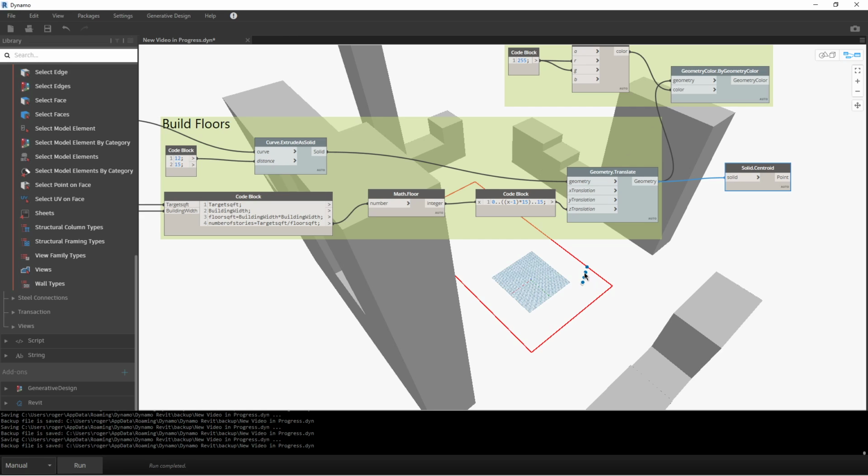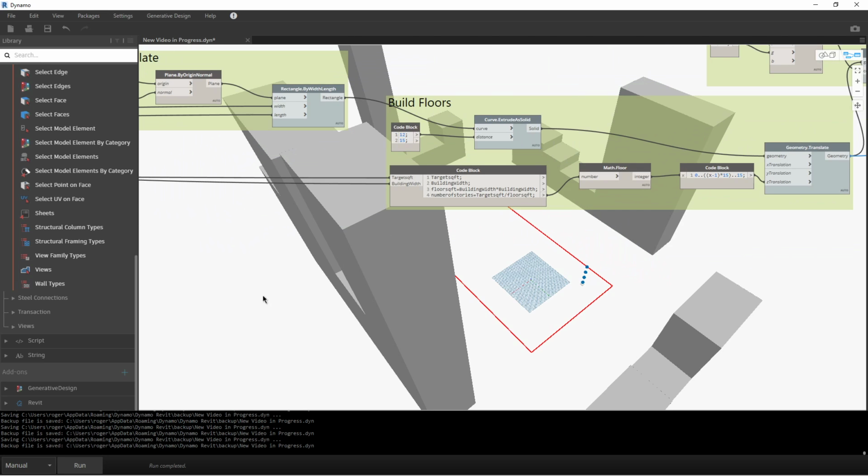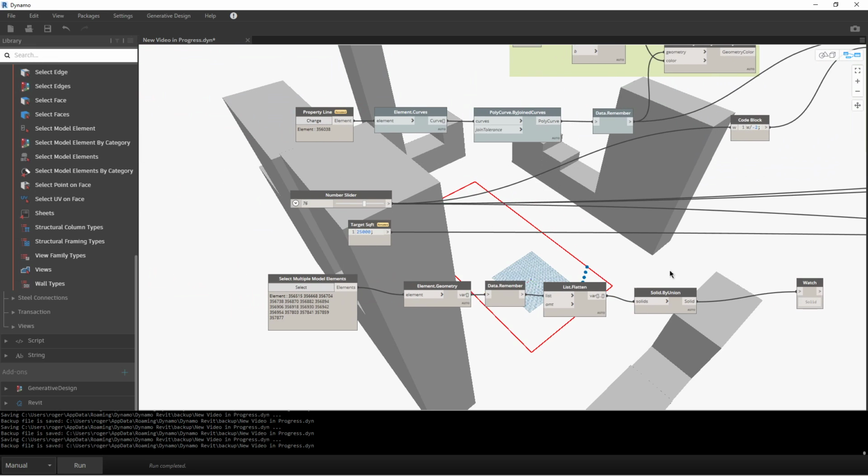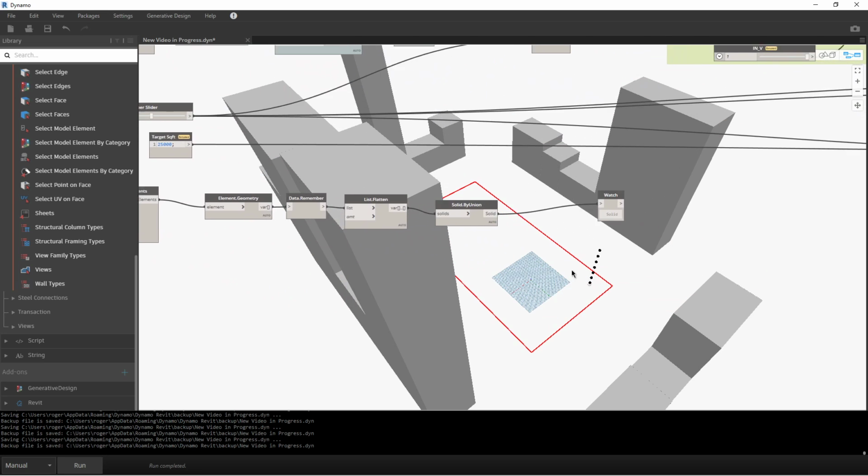Imagine now these are the center of each one of the floors. You know, that would be a 12-foot floor, so it's at the 6-foot level, right in the center of the building, and then looking out from that building to see whether that sight line hits something else. And we have 4 floors now, so we have 4 points. If we go over here and change obviously the width of the building, it's going to get taller, and if we rerun it, we get more points. And you notice how it also jumped closer to the corner of the lot. So